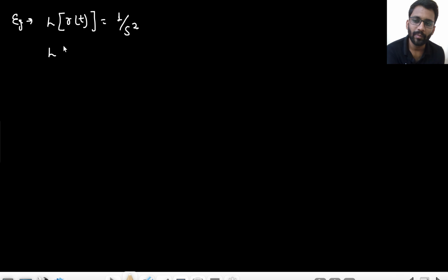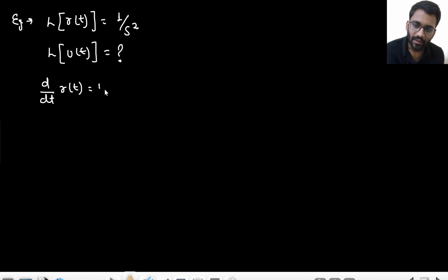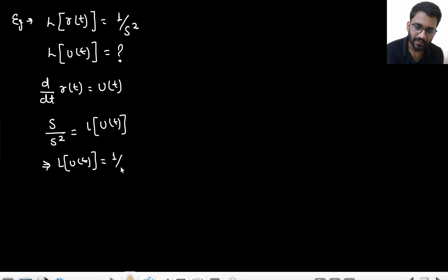Okay, so Laplace transform of r(t), you tell me, what is the Laplace transform of r(t)? That is 1 by s square. Now what will be the Laplace transform of u(t)? That I need to find. Okay, so what I will do, d by dt of r(t) is u(t). d by dt means s will be multiplied, so s upon s square will be the Laplace transform of u(t). So from here you are getting Laplace transform of u(t) will be 1 by s.